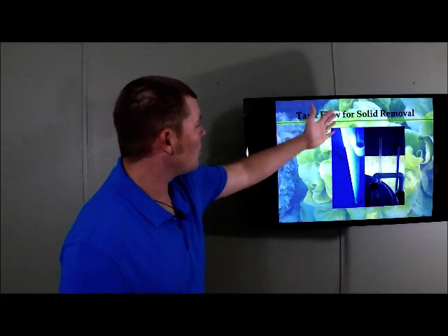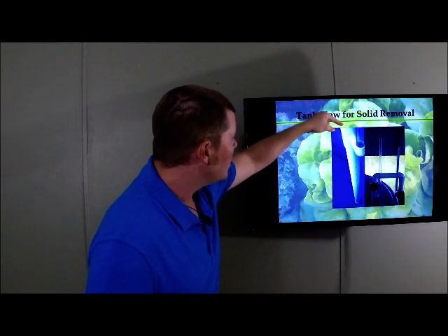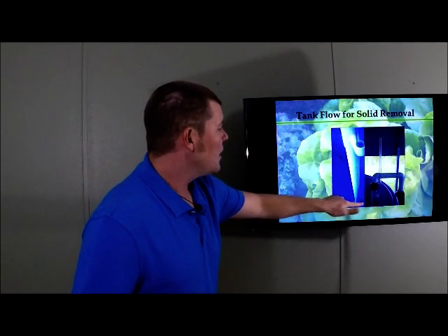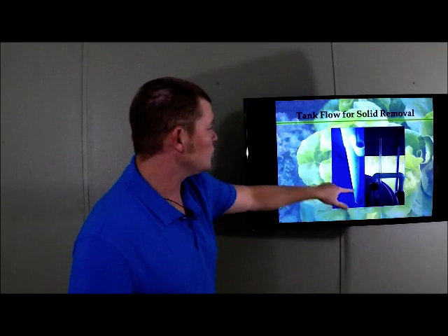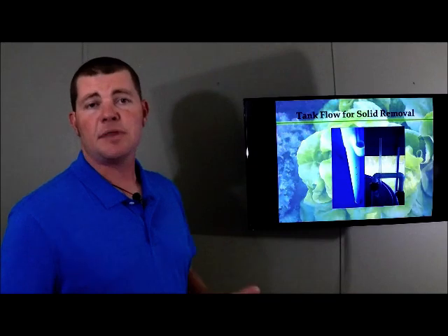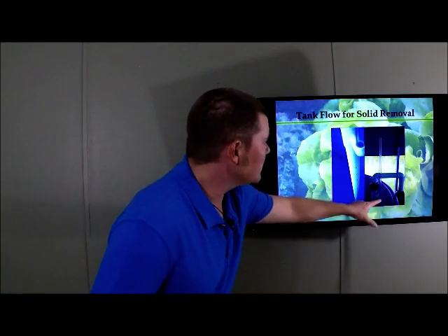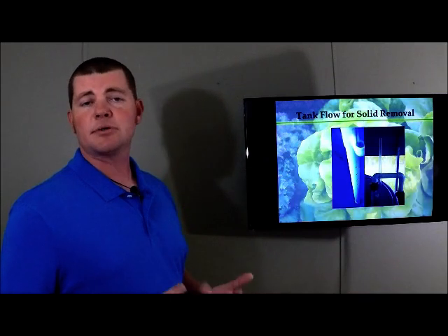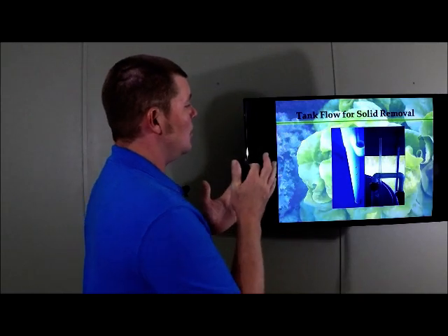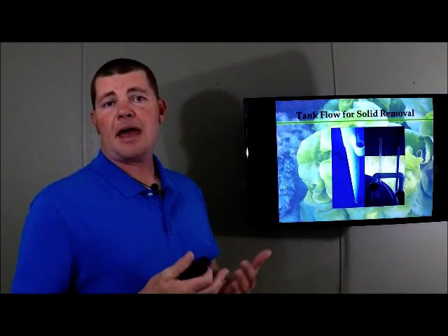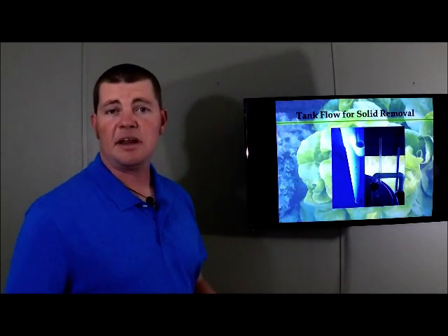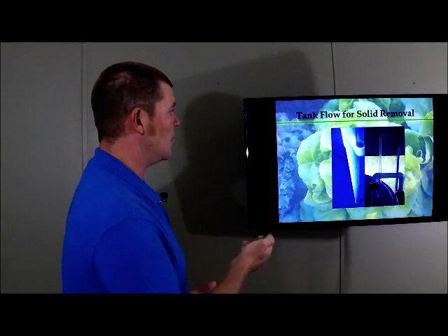And here's a picture of our water outlet. As you can see, it goes all the way to the bottom of the tank. It's capped off, and then we have the correct number and size of holes drilled in that distribution outlet so that we create the right velocities within the tank. And here is a manometer, and we will talk about that a little bit later as well. That's basically a means to look at the flow rate that is created by creating differential back pressure through a reduction fitting. And we'll talk about how to build that a little bit later as well.